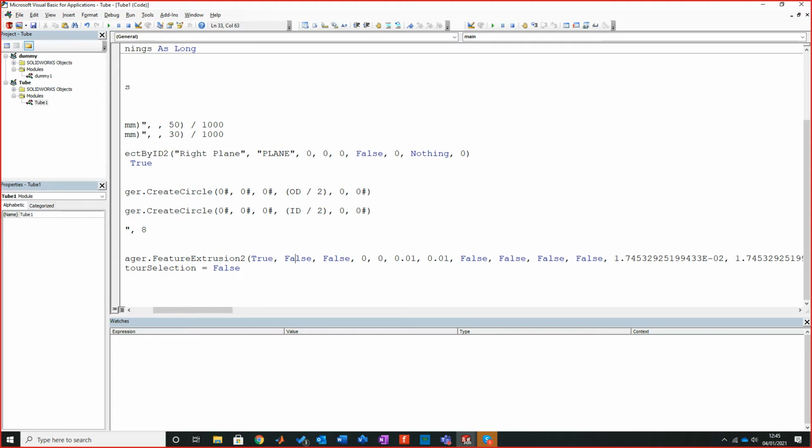Now these are what the nickname is, start and end point extrusions. Think of it as a line again. So you have a start and an end point, and what it's referring to is drawing each start and end upwards. So you can do this with just one, but if you were doing a mid, you can actually get it so it'll extrude one side by 5 millimeters and the other by 15 millimeters. But for this, we just said it'd be 40 millimeters.